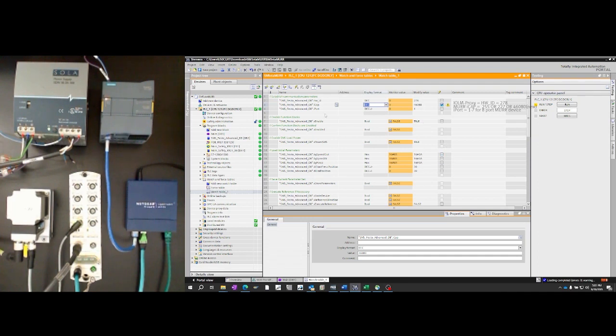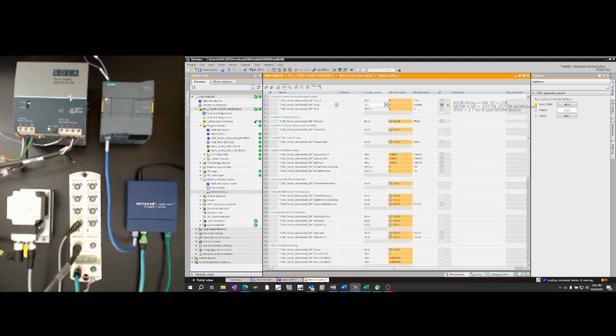You'll also see I have a sequence here for enabling the function block, supplying load power, not logic power, but load power to the unit, some initial parameters, saving those parameters, referencing the actual servo unit inside the stepper servo unit, and then executing in and out motions. In order to do this, I need to put my PLC into run mode. You can do this from the testing tab on the far right. It'll prompt you to say, are you sure? Yes, we are.